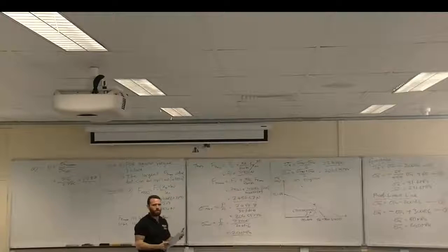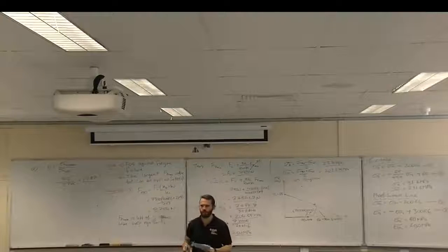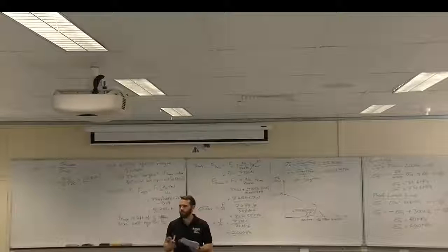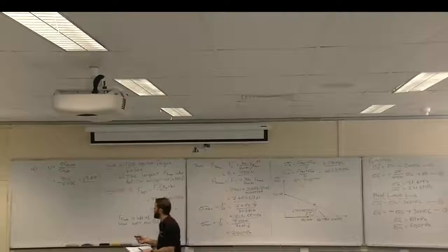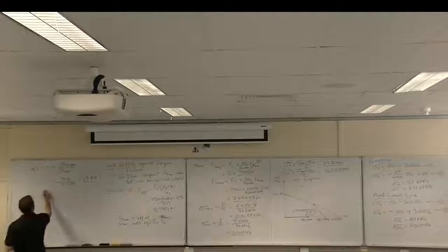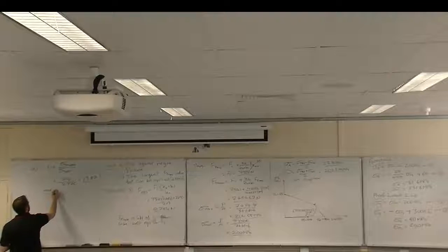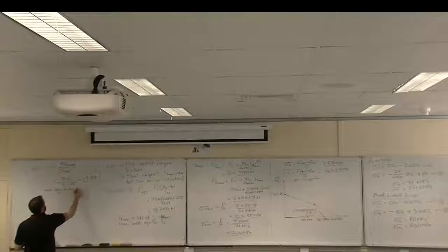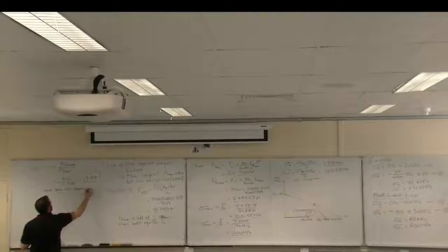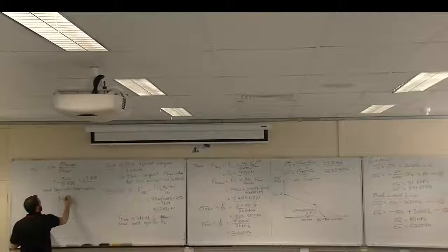So is that more or less than our factor of safety against separation? Remember the factor of safety, what was that, 8.7? Factor of safety against separation? So you would probably say, and separation n equals whatever it was, 8.7 I think it calculated as. So that one's the more critical.